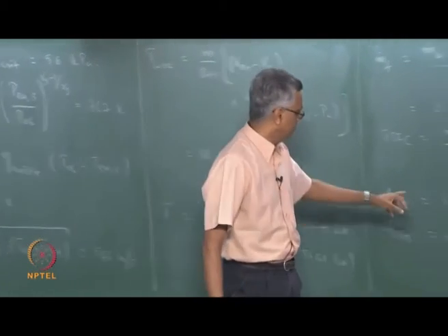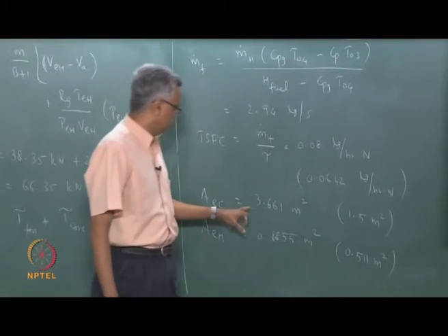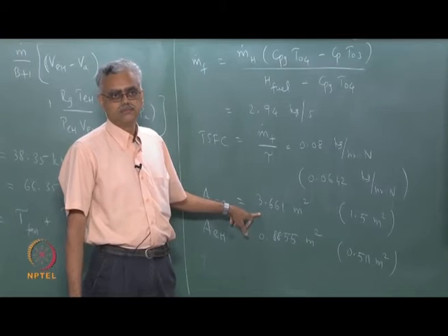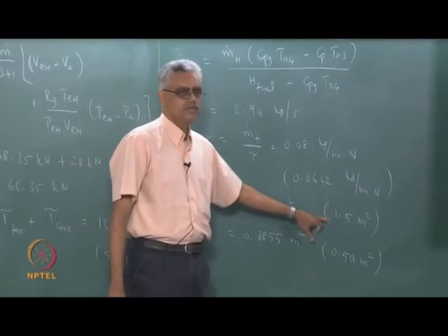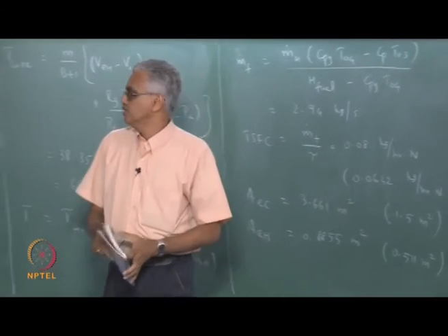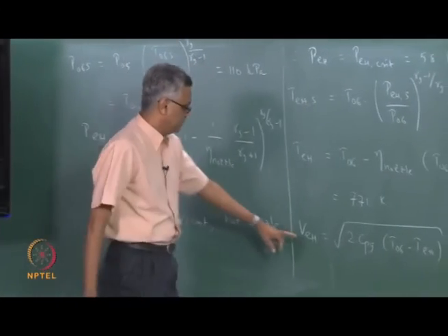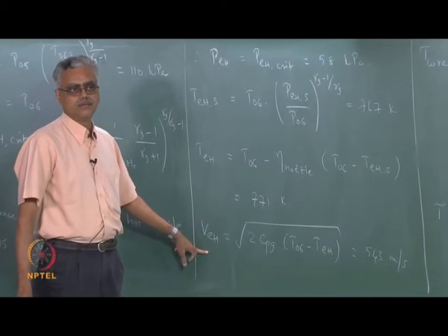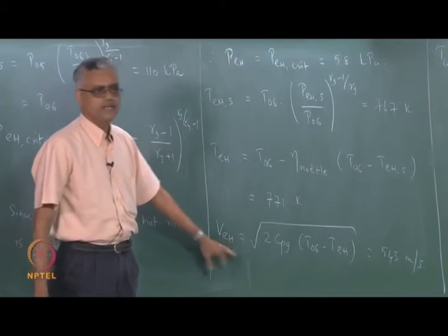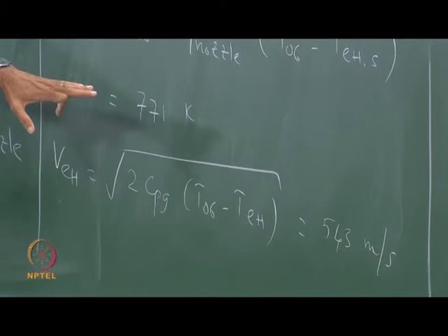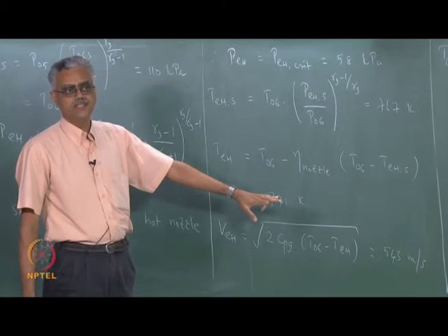So, the same nozzle must pass that mass flow rate. If you start with the fan nozzle, we can simply scale down the mass flow rate to agree with this. Remember our exit velocity and other things that we calculated. For example, if you look at VEH, mass flow rate was not involved in these kinds of expressions, so VEH is not going to change.